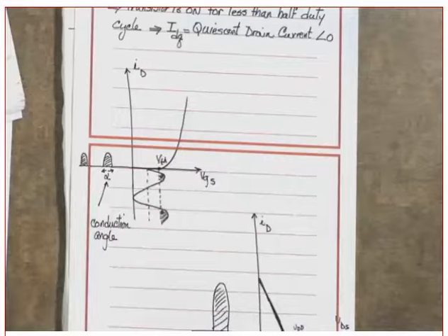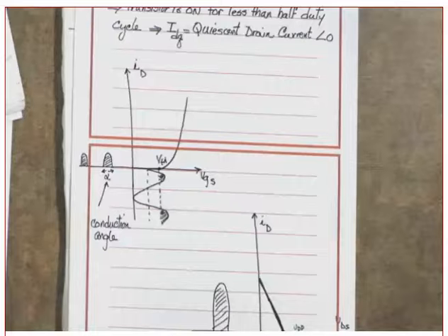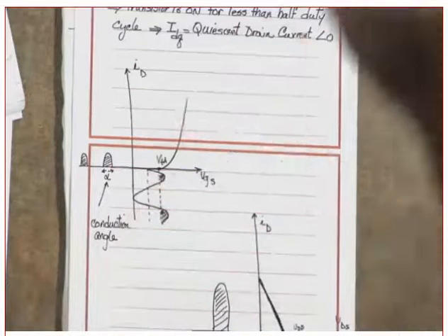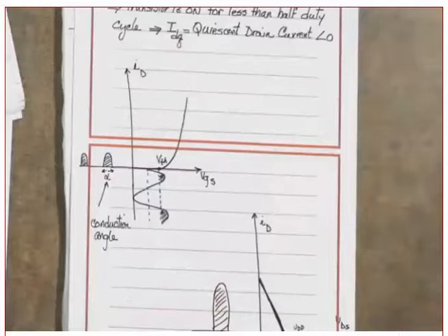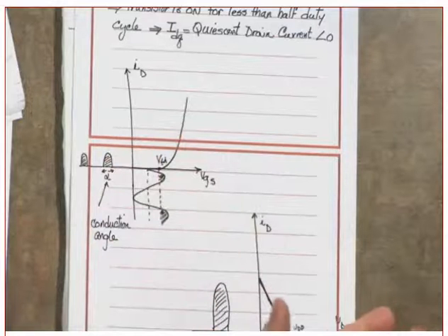Okay. We will see in just a second that when alpha approaches 0, what does it mean? It means the transistor will not conduct. Yes? We will see the efficiency approaches 100%. Yes? But at what expense? At the expense that there is no power delivered. Do you understand that or not? There is no power delivered. What power? When I say power, what power? The RF power. There is no power delivered.